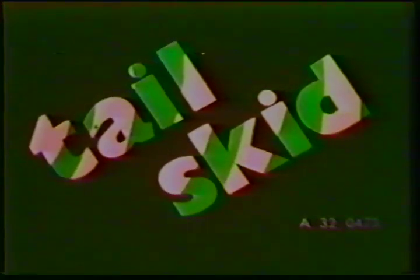A few words about the tail skid, which is installed to protect the tail cone from an excessive body angle on the ground. It is merely a shoe which is not retractable, covered by a fairing. On landing with the struts compressed, a body angle of approximately 13.5 degrees will help polish your shoe.